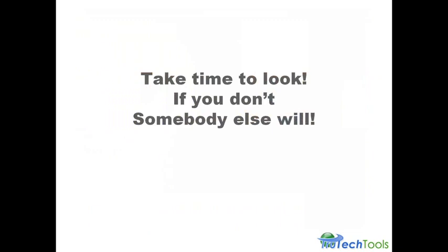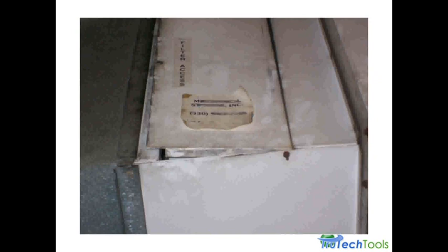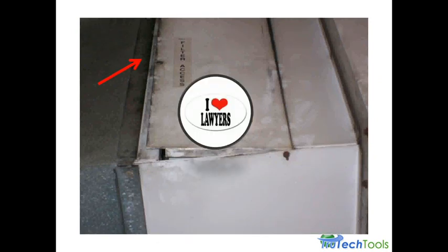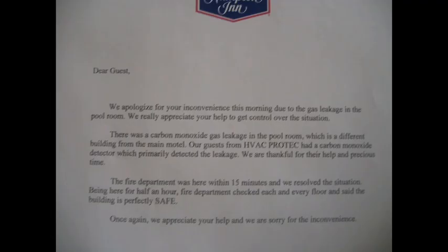The moral of the story is if you don't take time to look, somebody else will, because here we all are, 25 guys looking at this thing. And this guy may as well just put up a sticker when they left this door open that says, "I love lawyers," because here's the hotel saying we just had somebody out for service and they didn't find any of this stuff. They're all upset. The guy changed the filters, leaves the filter door open, doesn't connect the makeup air, doesn't check the makeup air for the boiler. So if you want to leave yourself a liability, don't learn how to test properly.